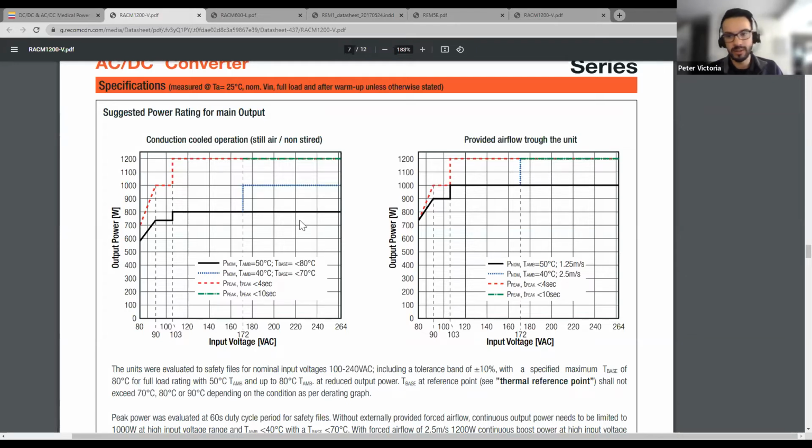The other interesting thing about this part is it comes with the PMBus interface, which is similar to I2C. This essentially allows customers to either monitor the part, control it, or configure it. If they want to adjust the output voltage or set a certain ramp rate for the output load, all these things are possible. Or if they want to monitor the output voltage or the temperature to make sure it's all good. That's a new feature for us with this part, and something we're really excited about, and we think it's going to help a lot of people out and meet a lot of different requirements. So this is definitely a good one, a winner.